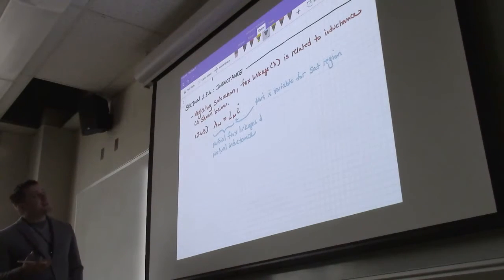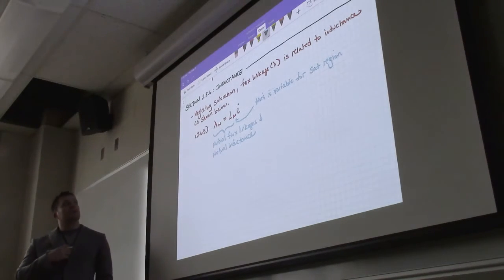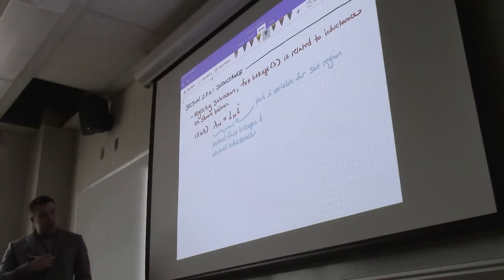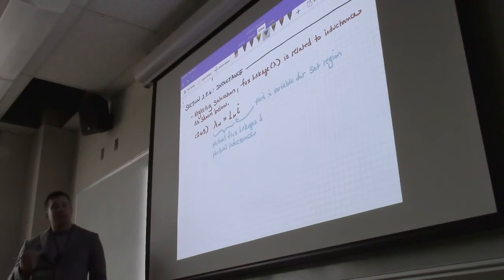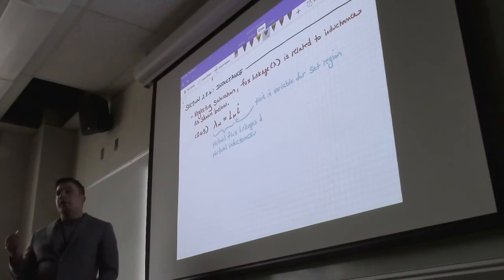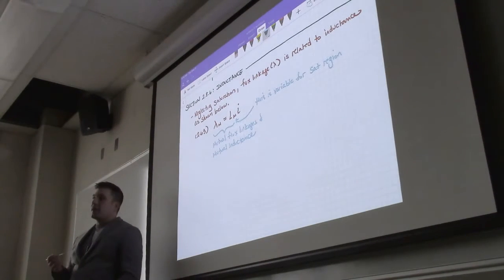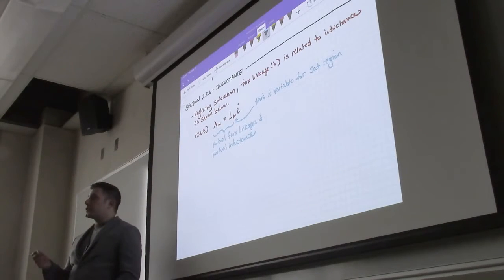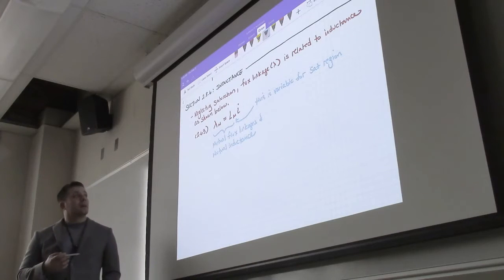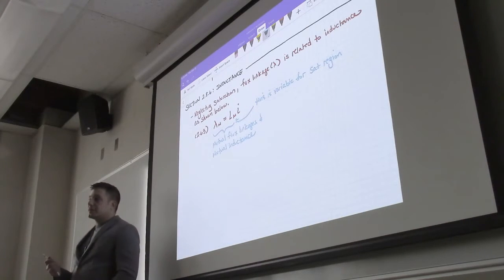We said that this expression holds neglecting saturation, and the reason for that is because in the saturation region there is no single inductance value that would represent this relationship here, right? We would need a varying function to describe the inductance value.